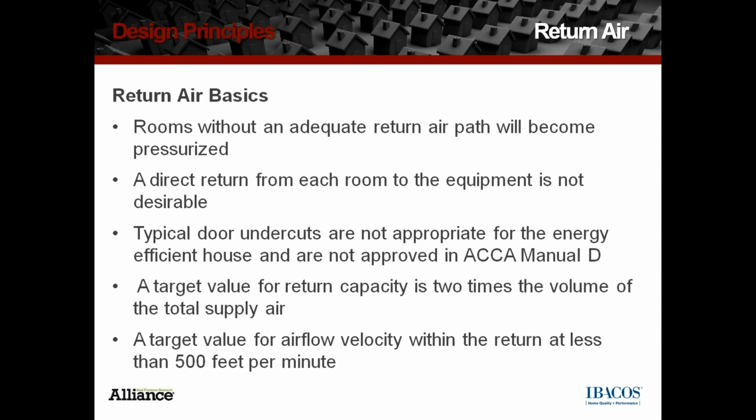The classic story about this is mom puts baby down for a nap in the room and closes the door, comes back in and the room is hot. This is a room that wouldn't have a clear way back, utilizing a door undercut or some ineffective method of getting air out. What has happened is that room has become pressurized, the supply air has slowed down and gone to other places in the house, and the room has heated up, and baby wakes up sweaty.